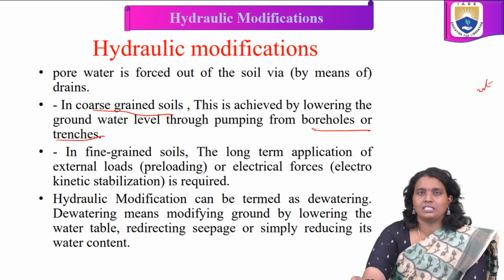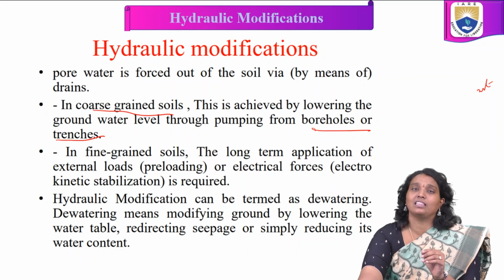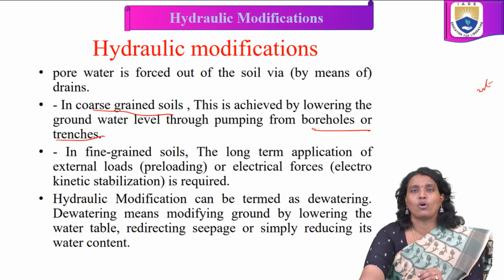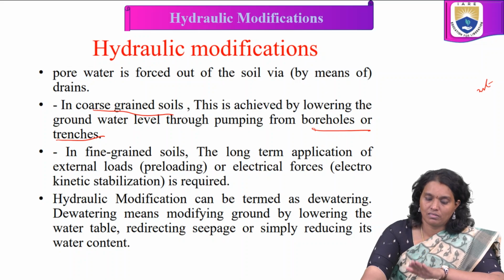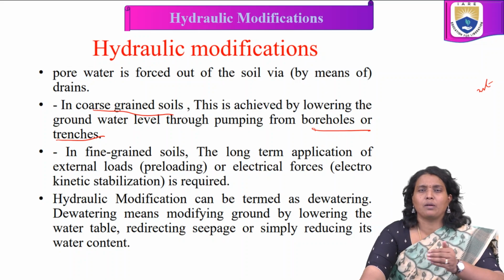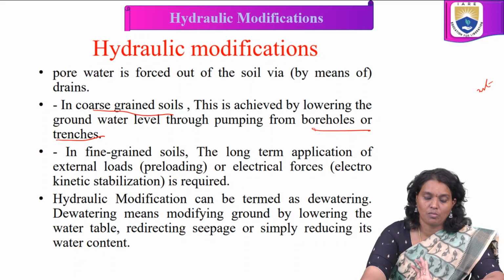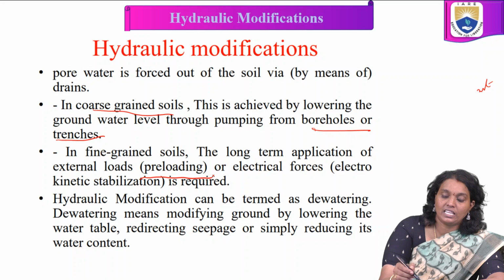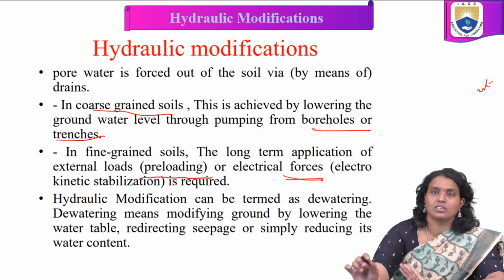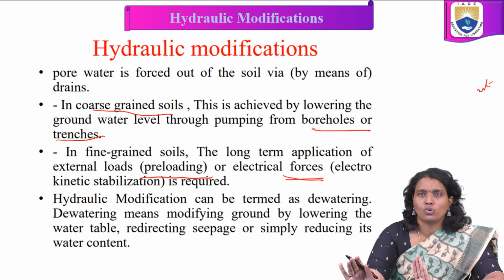Coming to fine grained soils, it depends upon which type of soil condition there is in the region where we require the modification. That also plays a major role. For coarse grained soils, we pump from boreholes or trenches. In fine grained soils, the long term application of external loads, that means preloading, or electrical forces, electrokinetic stabilization, is required for hydraulic modification.